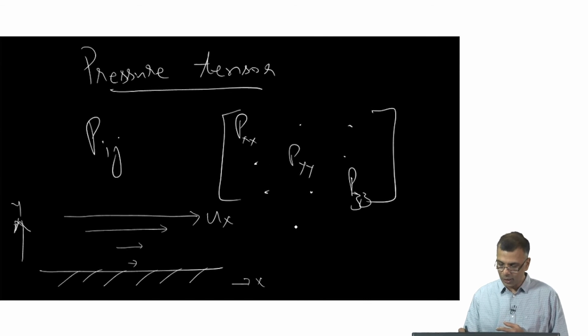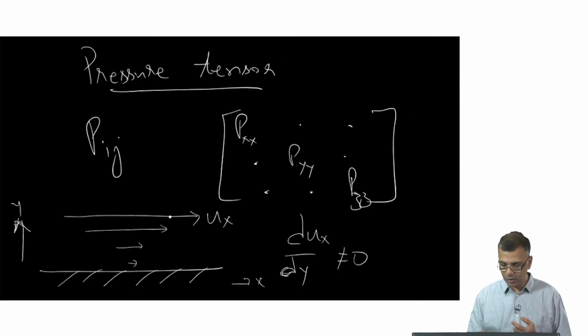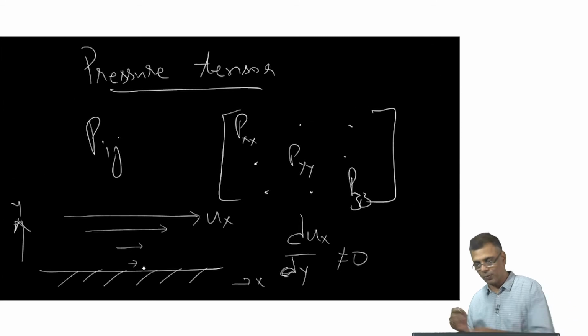In other words, these cross terms are non-zero. So, this represents shear. If, on the other hand, you have a relatively less viscous fluid, say water, you would think that this gradient is not as large. It's almost as if these vectors are almost the same length, and right at the surface the fluid is able to slip rather freely.